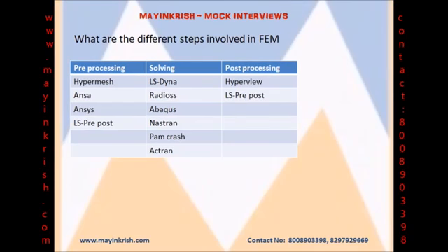The second phase in finite element analysis is solving. The operations in this phase are performed by the FEA software. The FEA program renumbers the nodes in the mesh to minimize computational resources by minimizing the size of the global stiffness matrix. It generates a stiffness matrix for each element and assembles the elements together so that continuity is maintained, to form the global or structural matrix.